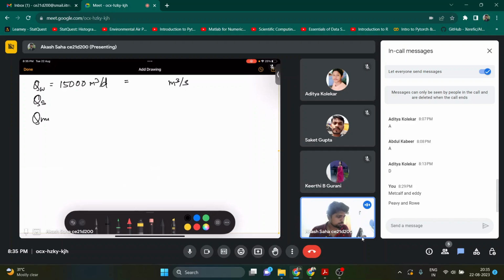So my Q mix will be QW plus QS. Now what will be my BOD mix? My BOD mix will be the BOD of wastewater times Q of wastewater plus BOD of stream times Q of stream, divided by Q mix. From this I will get the BOD mix.